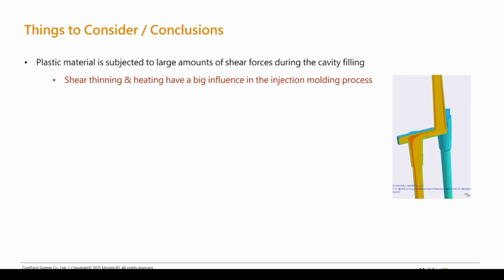All right, wrapping things up, plastic material is subject to a large amount of shear forces during the filling stage of the molding cycle. Shear thinning and heating have a big influence on the injection molding process, not necessarily only from a surface defect point of view, but also from a progression point of view. We saw a shear-induced imbalance. We also saw shear marks. We saw a bunch of different effects that are all caused by the shear forces experienced by the plastic during